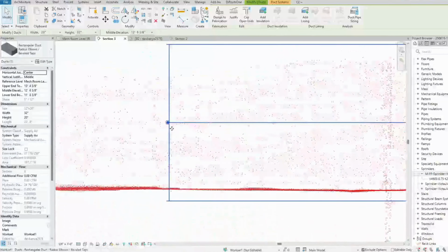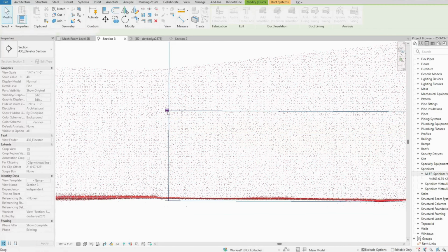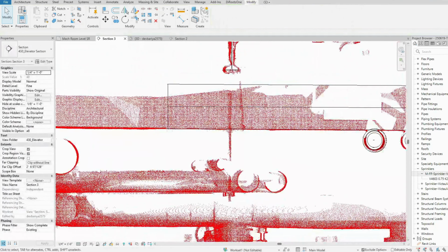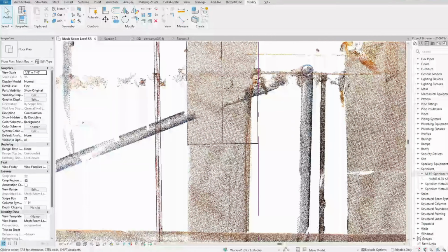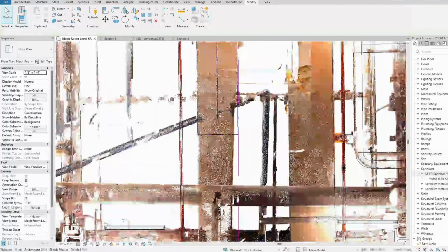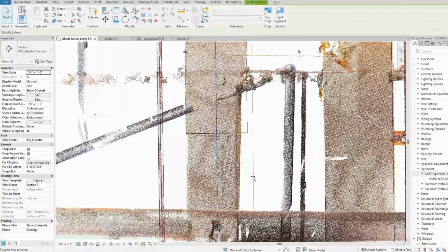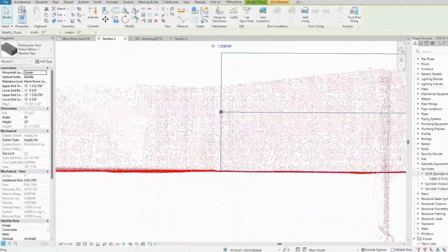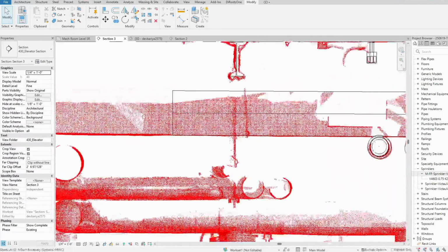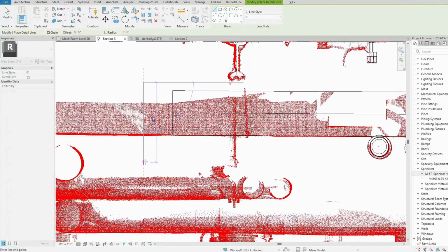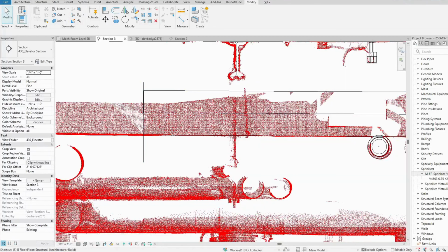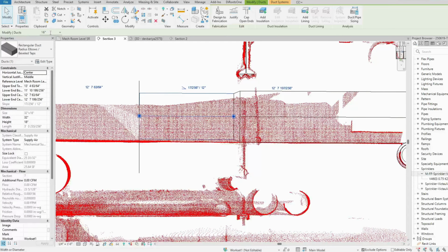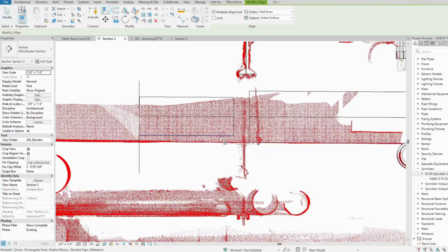Let's begin with the setup. Make sure you're working in a project template, preferably one that includes mechanical families and systems. Now open your mechanical floor plan, Level 1 view. This gives us a good horizontal layout for routing ducts. Go to the Systems tab on the top menu and click on the Duct tool. Here, you'll see multiple options. Choose rectangular, round or oval duct types, depending on your project needs. For this demo, we'll stick with rectangular ducts, since they're most commonly used.